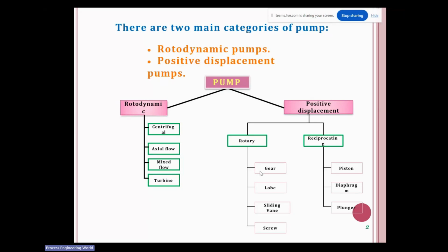Sometimes, if we have a solution and we decrease the temperature or evaporate some of the solvent, you will see solid deposition or precipitation start. In some operations you need to evaporate the solvent, and as it is removed, the solution reaches the saturation point where the dissolved solid is no longer dissolved. It starts precipitating and agglomeration occurs.